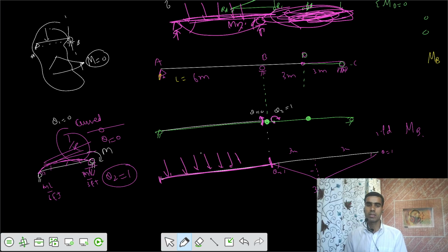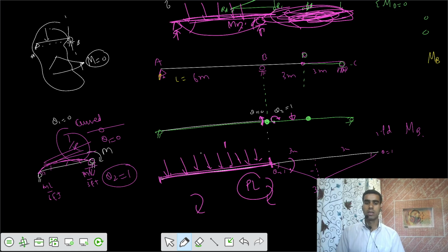For all values of x, anywhere you take the point load, the unit load, you would have a moment of 0 up to this point. But as soon as it reaches somewhere here, we can have a moment of P into L anti-clockwise in this fashion, about this point. That's why the theta developed here is in the same direction, because if the load is somewhere here, the moment developed would be in this fashion about the point B. So that's why we write the theta in this fashion.